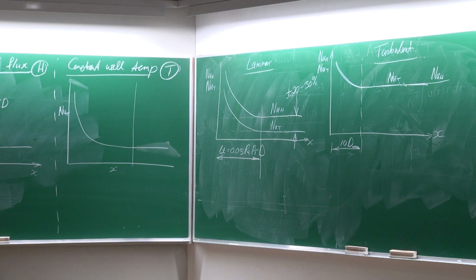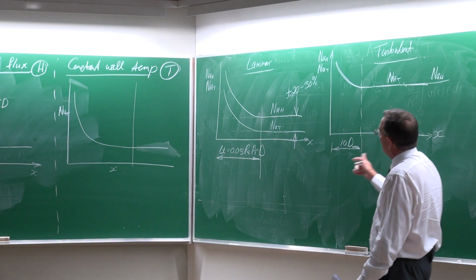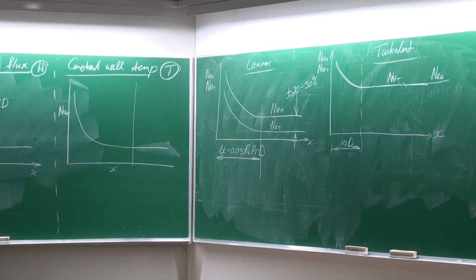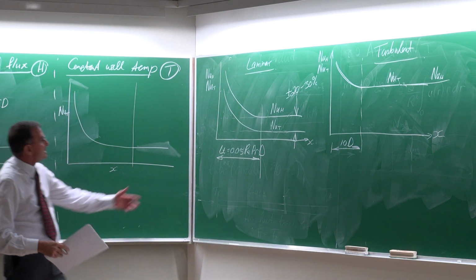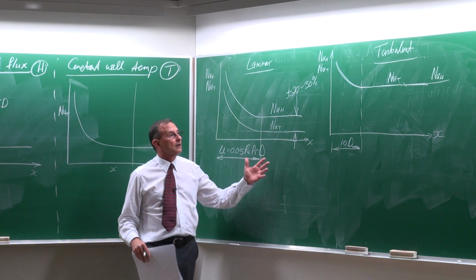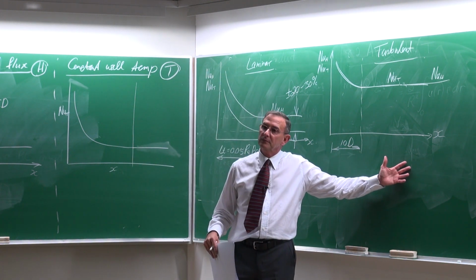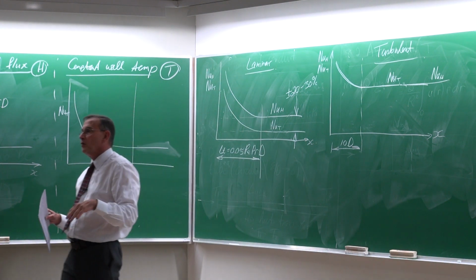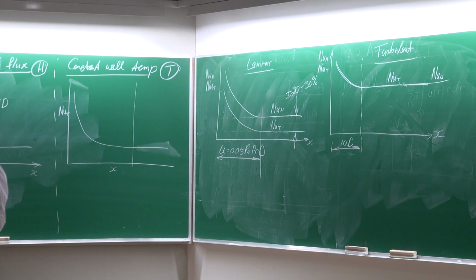So what is the bottom line? The bottom line is that the type of heating and or cooling condition that is going to be used, constant heat flux or constant wall temperature, has a significant effect in the laminar flow regime. Okay, but not in the turbulent flow regime. So normally, if you calculate the Reynolds number and it's turbulent, then you can say for yourself, yeah, I've got some less work to do. I don't have that much to calculate. It's easier.